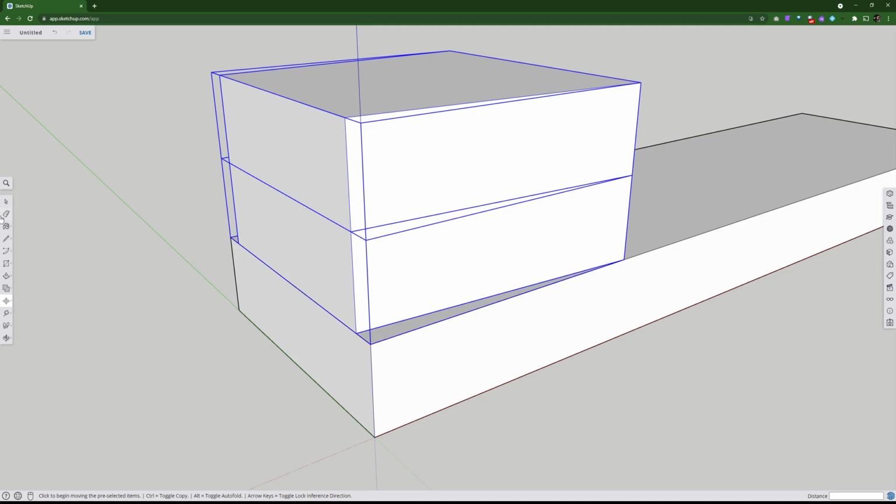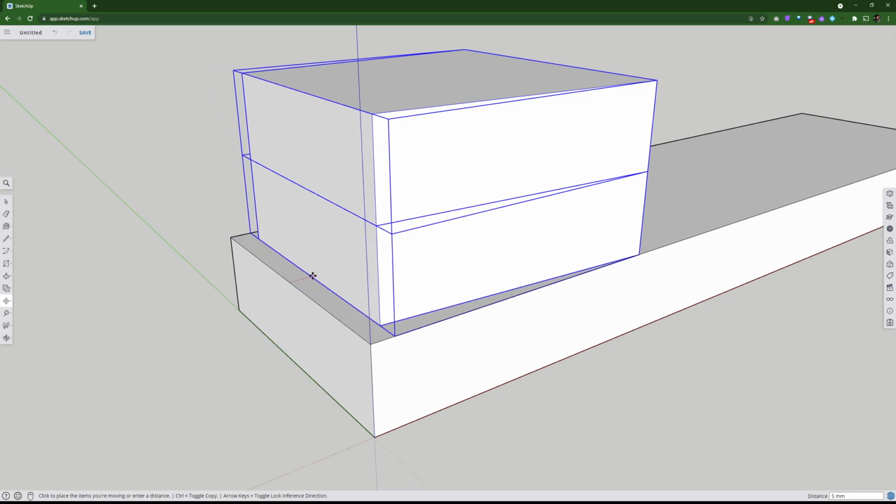They're both selected blue. I can just pick one, but I want two, so the way I do that is I select, hold down shift, select another one. See a little plus and minus added? I can unselect two. Select what I want. Okay, so with the two parts here, blue selected, I'm going to click on move, go to my midpoint, and then I'm going to move it back on the red axis, and I'll come back 5 as well.